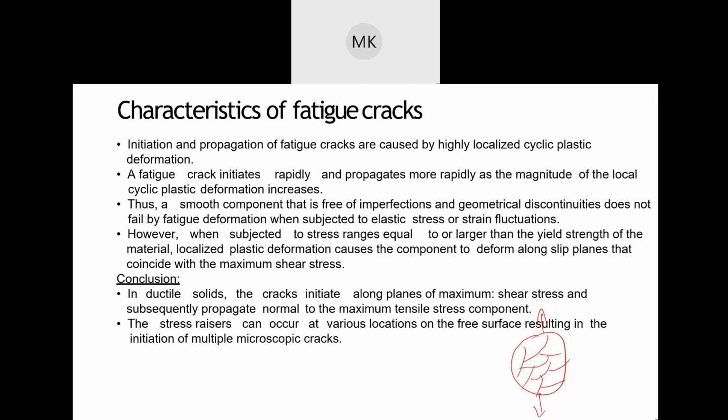The minute I start fatiguing, depending on what kind of material and what stress, you are going to generate voids at different areas, because you're starting to have dislocations created in different grains. So all the dislocation, what it means is you are displacing an atomic position from point A to point B, and thereby creating a void over there of atoms.